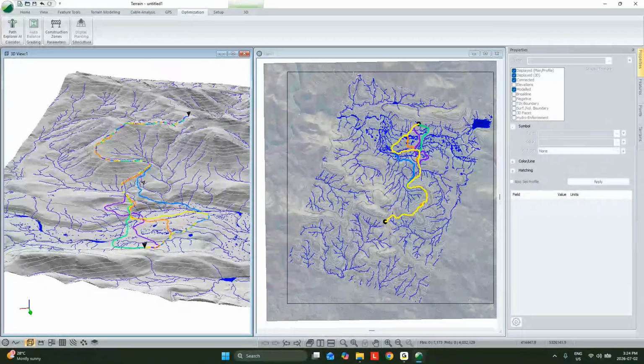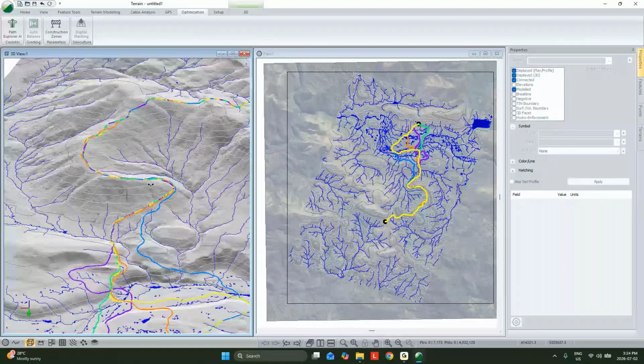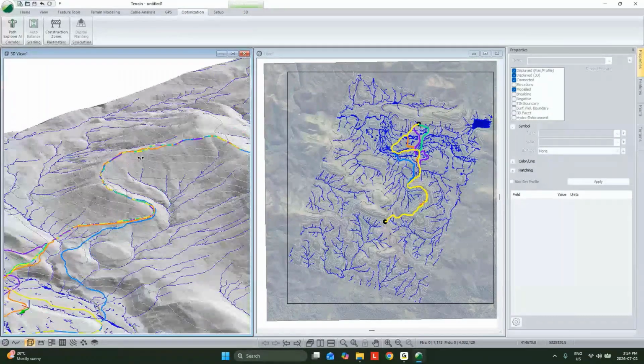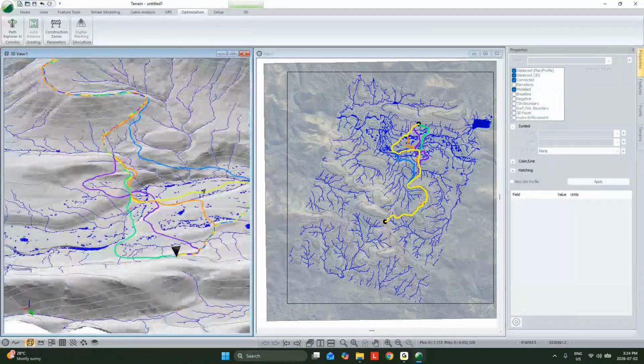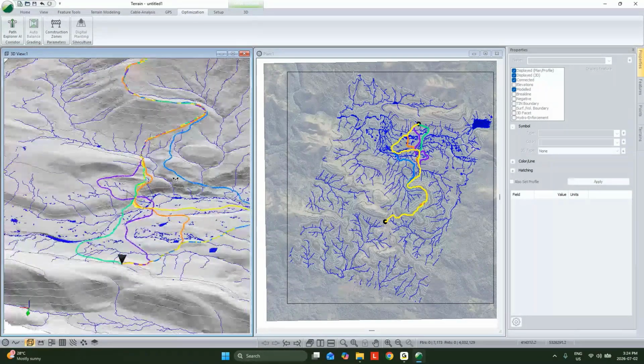Yeah, we can see in this particular example, all the options to really have things significantly different happen on the north side of our project. And if we're sanity checking it, it makes sense. With our grades the way we have them, we're able to get on top of that ridge, which is going to be by far the cheapest solution, gets to where we want to go. But down here, we have a lot more flexibility to move things around without having an increased cost for those alternatives.